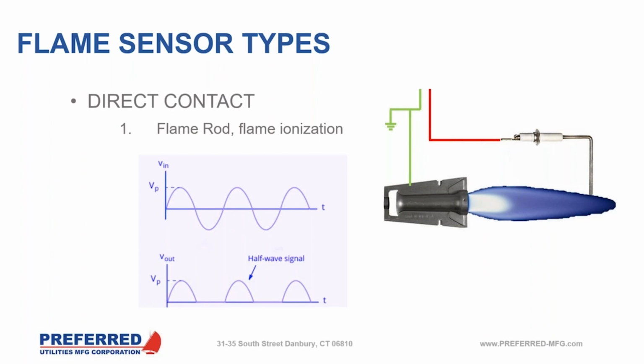Now, if it's operating correctly, and we start, for instance, a pilot or even a main flame, and we have the flame at the proper length into the flame rod, with that voltage applied, it is then going to load that signal, if you will. Inside the flame safeguard, it's allowing it to only load the negative side of the actual AC sine wave.